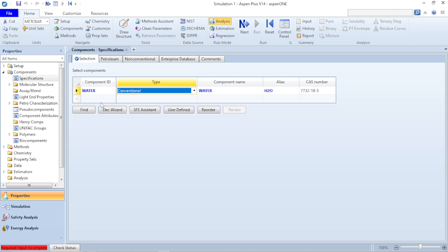But you'll be needing your proximate and ultimate analysis, and if you're going to be doing things like grinding and all that, you're going to be needing some PSD analysis. That's particle size distribution. So you'll be needing some of those parameters as well. All right, so let's go to the next thing.